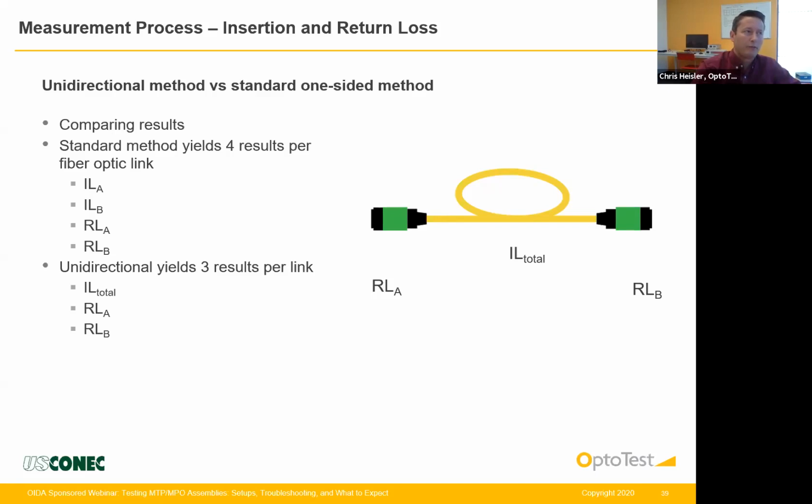If you reference with one type of adapter and then test with another, swapping adapters during your measurement process could affect your insertion loss values and cause them to go negative, which would make it seem like a gain. Other issues could be fiber handling.